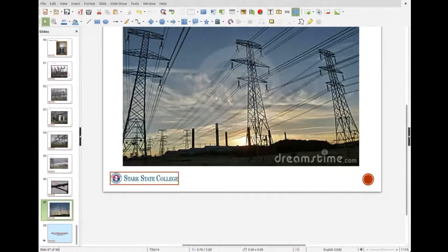So when you look at these big transmission lines, they just have 3 wires on one side and 3 wires on the other side, because each one of those is a separate circuit. The 3 wires on the left side is one circuit, the 3 wires on the right side is another circuit. And actually, if you see here, they got 2 wires running, so it might be the same circuit, or they might be 2 separate circuits, but most likely they're the same circuit, and they're just running 2 wires because of the amount of current that's got to flow through them. Right.